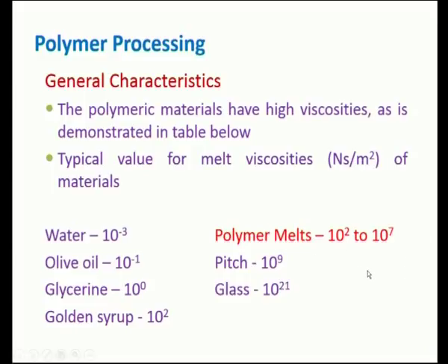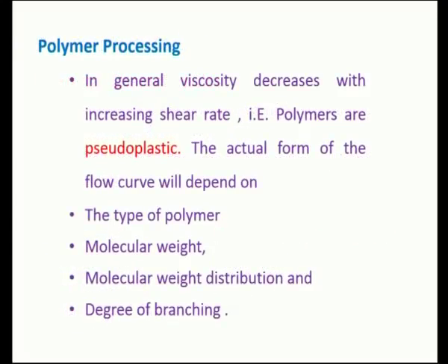So, that is a typical melt viscosity range all the commercially available polymeric materials do fit in. In general, viscosity decreases with increasing shear rate. When you increase the shear rate, viscosity decreases. Most of the polymers do exhibit such behavior. Such polymers are pseudoplastic.